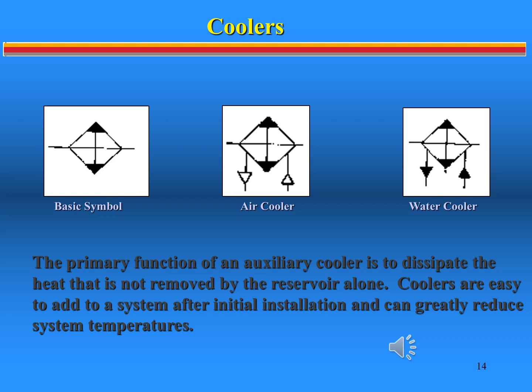In fact, coolers are often essential for designing temperature-optimized hydraulic systems that keep oil temperatures within a limited range. Such circuits are basic prerequisites for cost-efficient operation, as they provide a number of performance, economic, and environmental benefits. Maintaining the correct temperature keeps oil at its recommended viscosity, ensuring mechanical components are properly lubricated and hydraulic devices run at peak efficiency. Letting oil temperature rise beyond recommended limits can reduce the life of a system due to poor lubrication, higher internal leakage, a higher risk of cavitation, and damaged components.